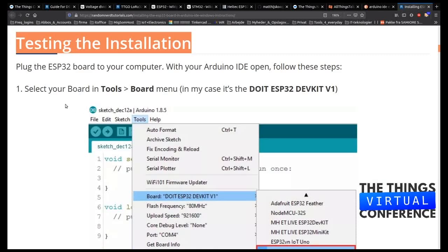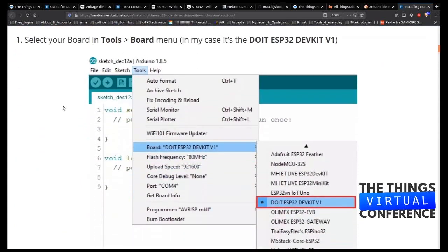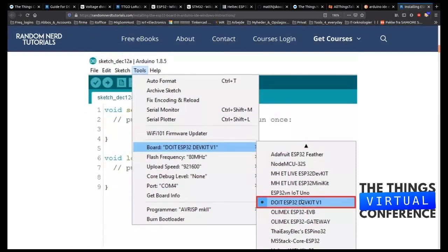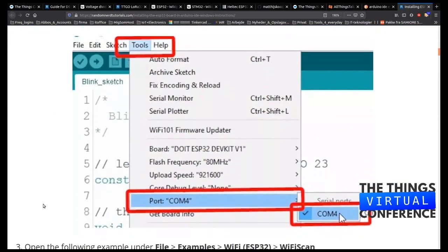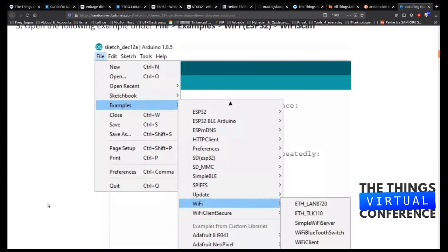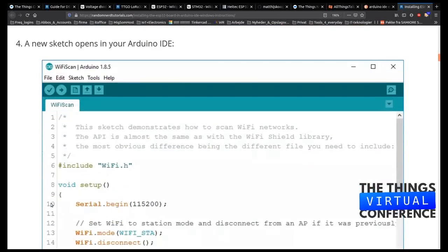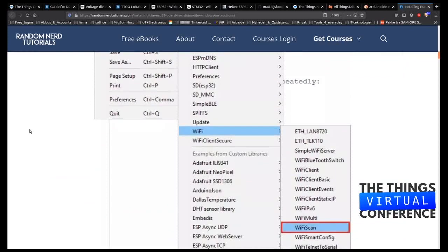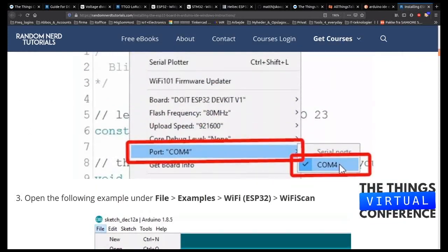You would say, okay, close the window. You would go into Tools, Board, and then on this list, you will select the development board you are working with. For instance, a Heltec Wi-Fi LoRaWAN 32 version 1 or a TTGO Wi-Fi 32, for instance. And if you have selected that, then there will pop up some other possibilities for doing some selections on communication speed, etc. So that's how you install the hardware support and select the board you work with.